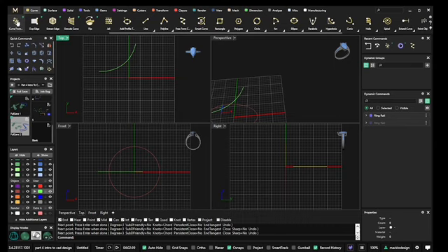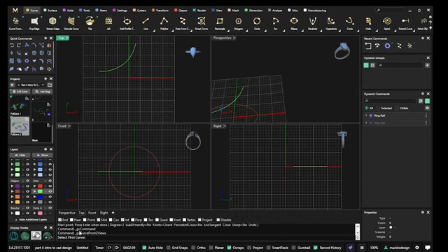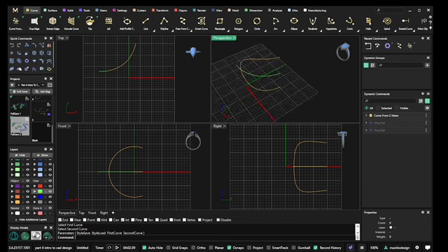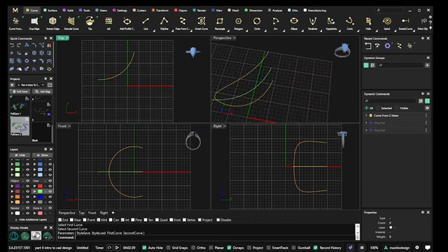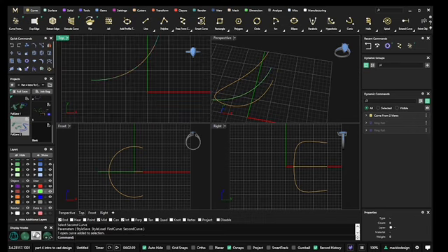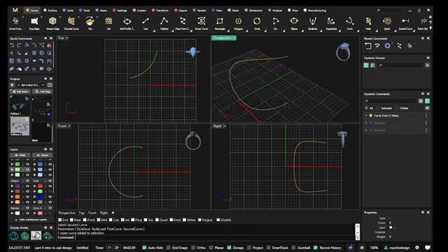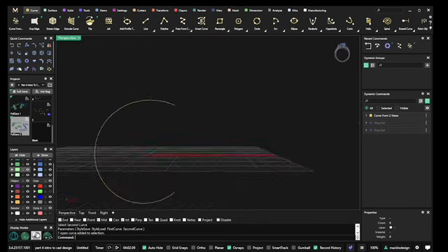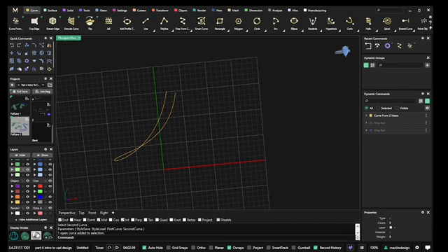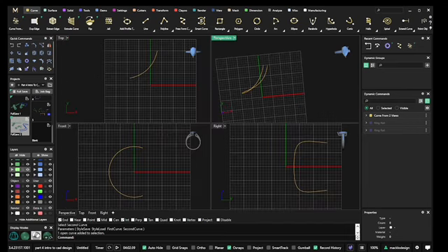And I am going to go back to my curve from 2 views up at the top in the menu, click on that, and the command line says select my first curve, select second curve, and look at what happened. So it took my curve that I created down here, the bright green. I'll turn that off. Oop, cannot turn off current layer. I will move my current layer and I'll turn off the green. So what you see here is the curve is in the shape of the ring rail and the shape of the curve that I just drew out there.